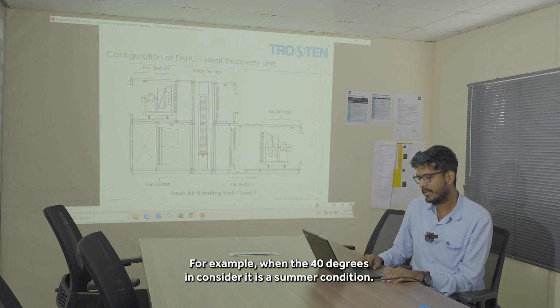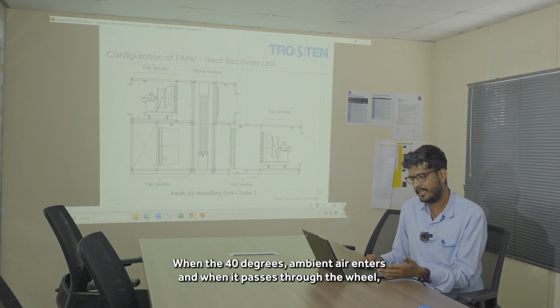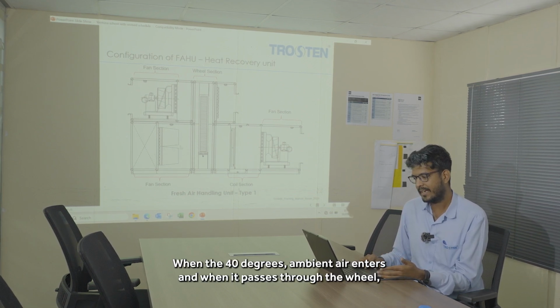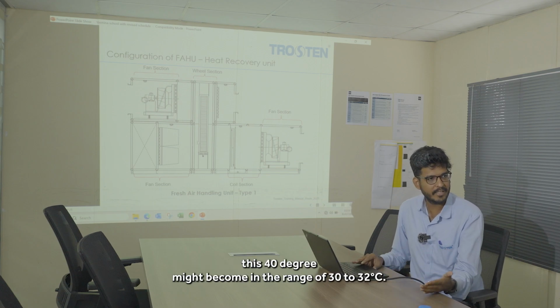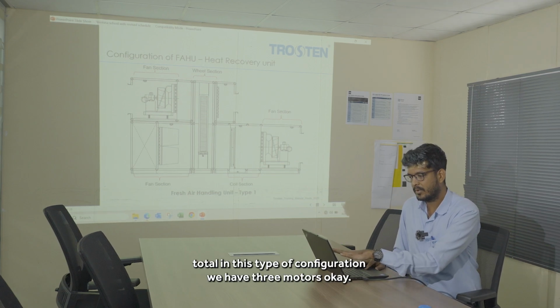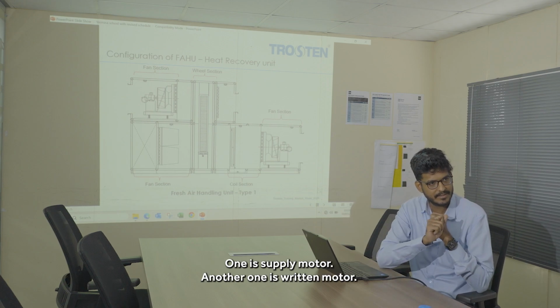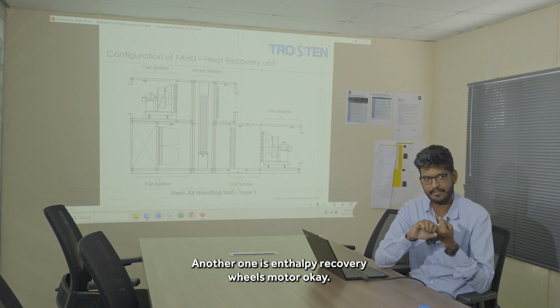For example, in summer condition, when 40 degree ambient air passes through the wheel, it might become 30 to 32 degrees Celsius. In this configuration, we have 3 motors: the supply motor, the return motor, and the enthalpy recovery wheel motor.